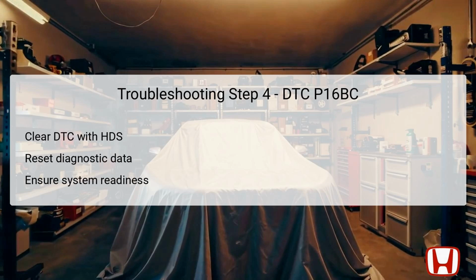In this step, you will clear the DTC using the Honda Diagnostic System, HDS. This process resets any recorded diagnostic trouble codes that may still be residing in the vehicle's computer. It is crucial to clear these codes before running new tests to avoid confusion with previously logged issues.